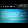Grit chambers are long narrow tanks intended to slow the stream so that solids, for example sand, coffee beans and eggshells, settle out of the water. Grit causes excessive wear and tear on pumps and other plant equipment. Its removal is especially vital in cities with giant sewer systems, which carry a good amount of silt, sand and gravel that wash off roads or land during a storm.